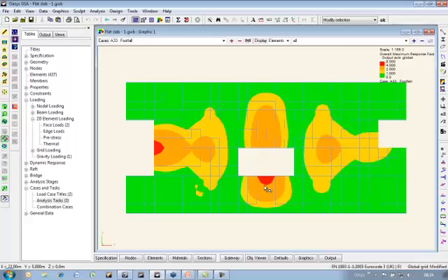And maybe if you're looking for higher requirements elsewhere. Now these corners are not actually showing any response at all. The reality is that in these corners they're actually vibrating at quite a high frequency, much higher than the 15 Hertz we chose, and you really need to take far more modes to get the detail into these corners. Something to watch out for.